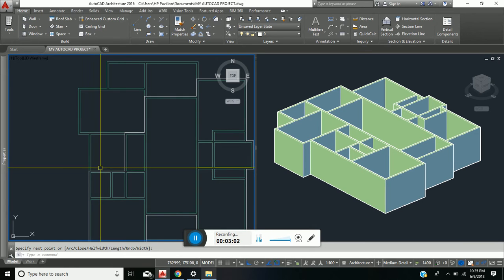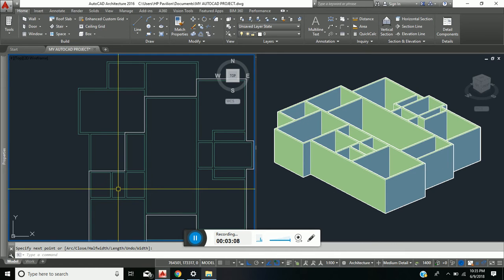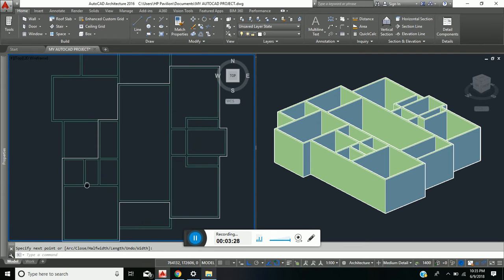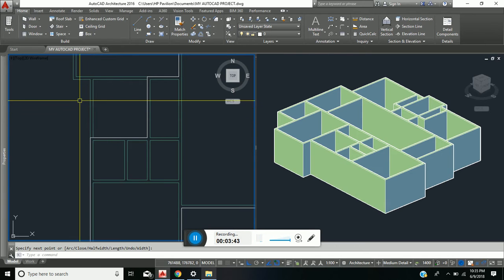In order to do that, it means all other walls would have to be reduced to heights of approximately 2,700 millimeters, that's 9 feet, and those walls would bear the slab roof portion of the building. Alright, so to do that, we had already drawn all walls having a height of 3,450, 11 feet 6. So we are now going to be reducing those walls that will be accommodating the slab roof type.